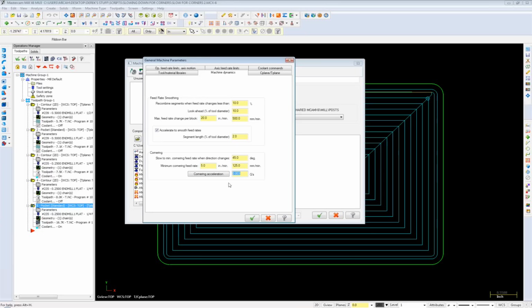Right. So now you've added about 6 lines of code, just coming from a straight and slowing down to the corner. It took that straight line that should have been maybe a line or 2 of code, and now might be 8 lines of code, because like you said, as it gets down, it has to start slowing the machine down before it gets to that intersection. It's complicated, but it does work pretty good. It's just everybody has different needs, to be honest. So it just depends what you want.